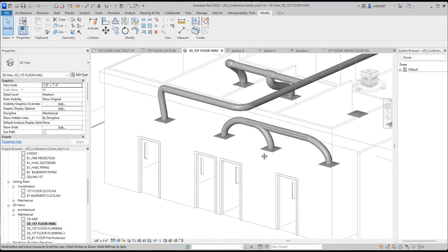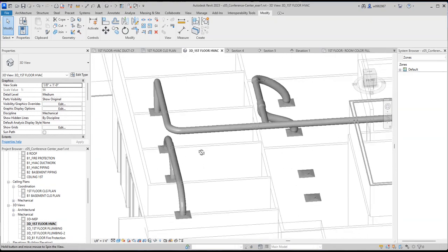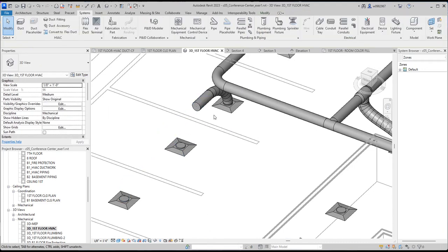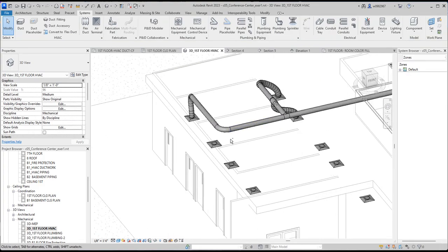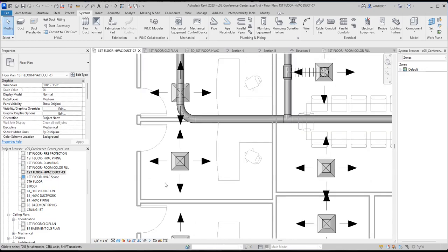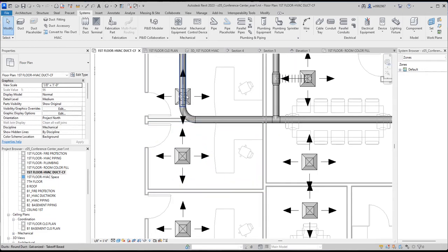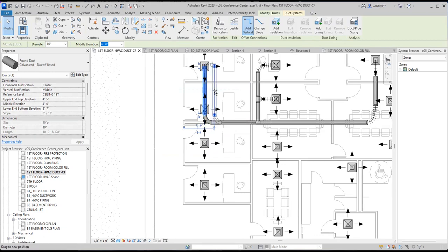Now all we do is make this join here. Okay, so again, now here, how do you want to connect this to that one? So I'll just delete this whole thing, and then find a way to connect these three directly here to the duct by going to my HVAC duct. This one is under, that's why it's giving me a different scenario. Anyway, maybe I can move that out of the way.